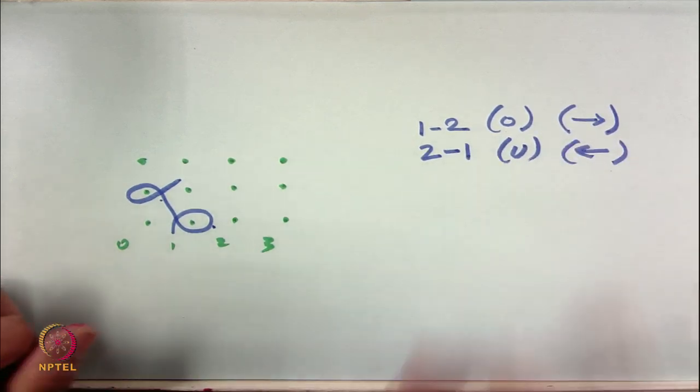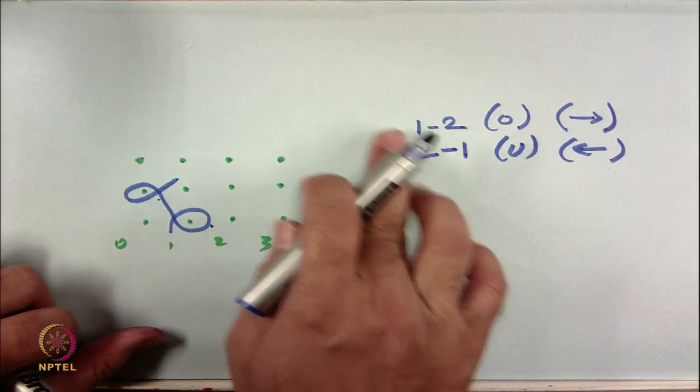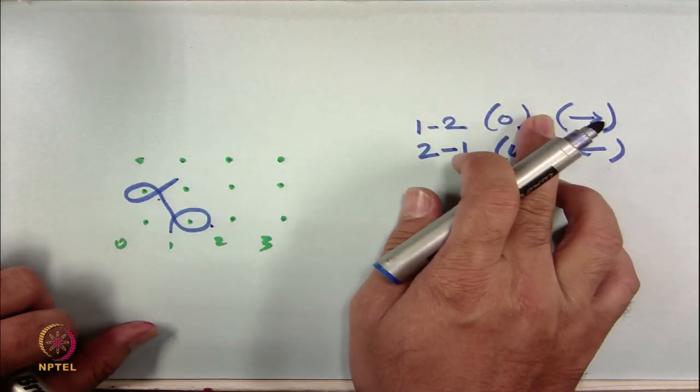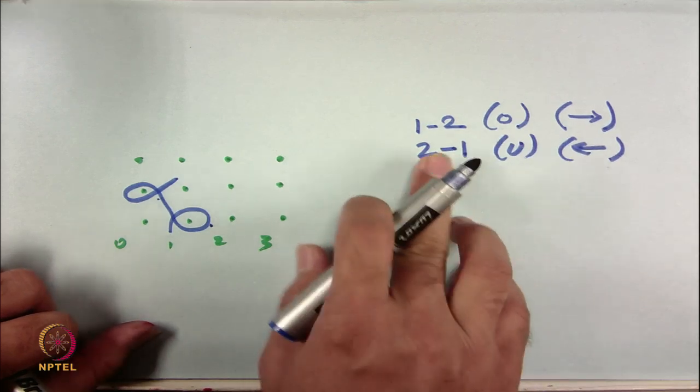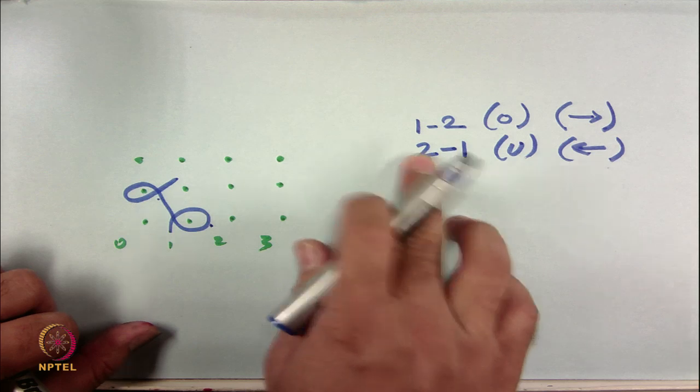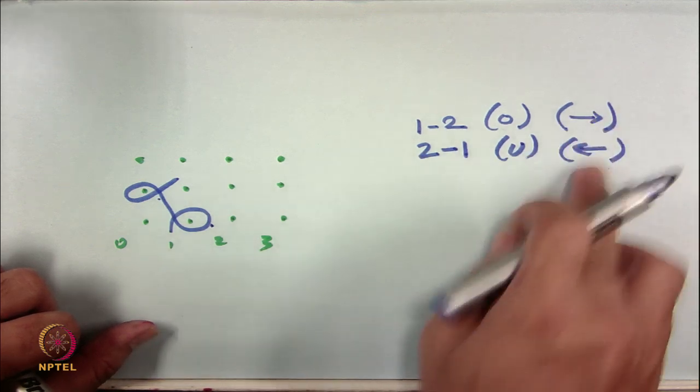So, the first shogging motion, the guide bar is shifting from left to right with respect to needle bed, and in the second shogging motion in the same course the guide bar is shifting from right to left. So, the directions are different.